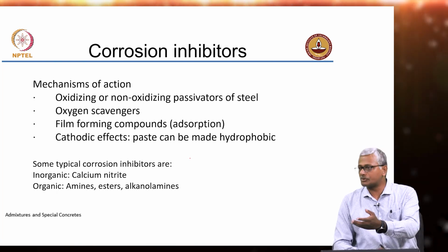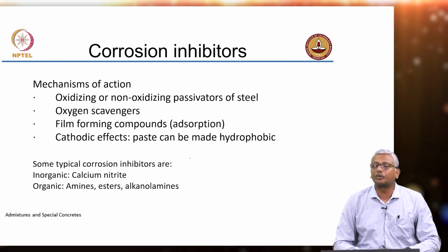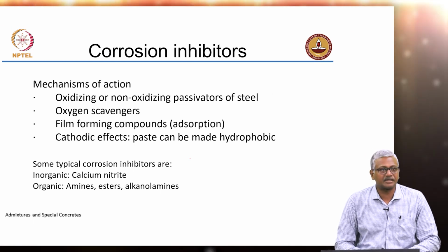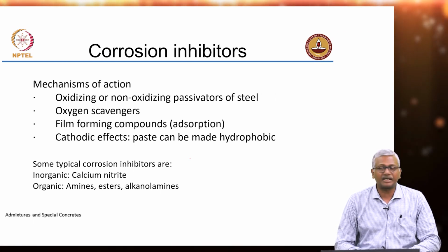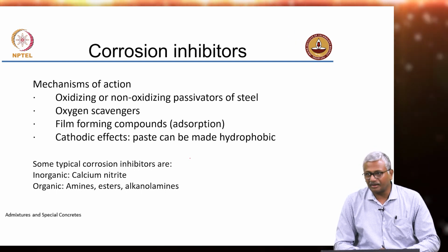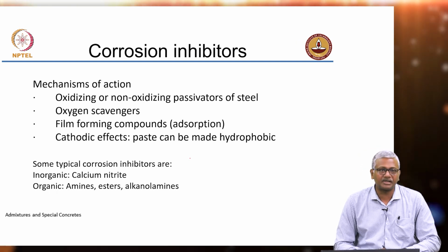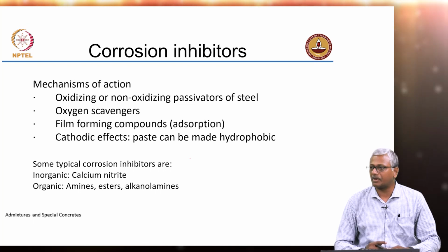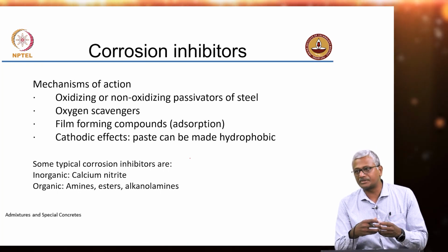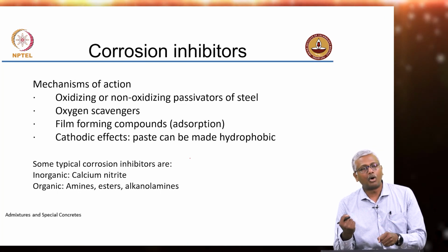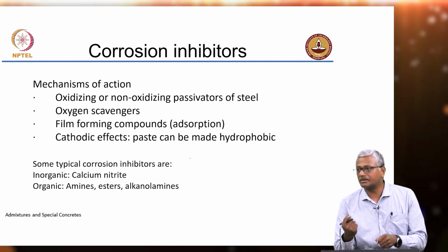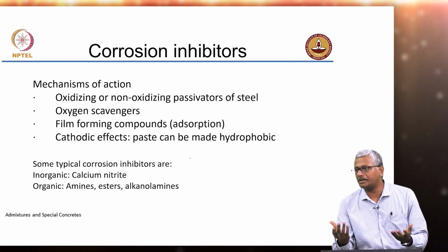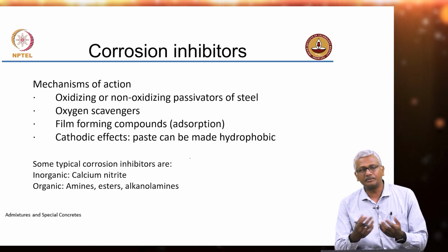There are also other approaches you may have seen, epoxy coating of steel bars. That's another approach. Now, that has to be done very carefully and very well, otherwise you are creating more problems than you are trying to solve. And any plastic or polymer coating on the steel will also reduce the bond with the concrete. Those numbers are very clearly shown in several research studies.